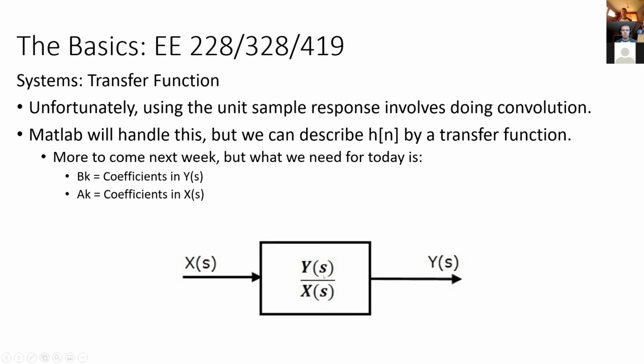We'll eventually go into what makes up these individual components, but not this week, I don't think. But if you're given a transfer function and you're told this system has these as the numerator coefficients and these as the denominator coefficients, that's really all you need in order to classify what it's going to do and to run it on any input that you can give it, like in MATLAB.